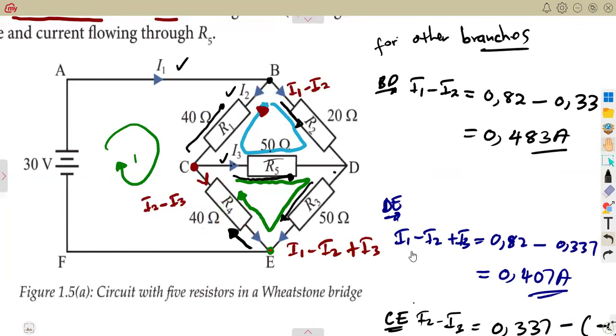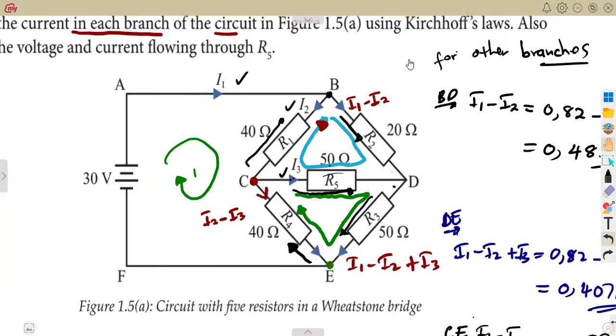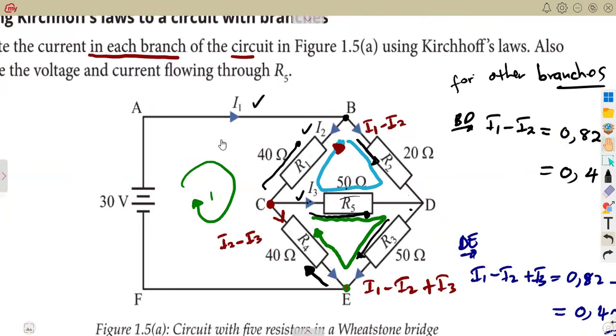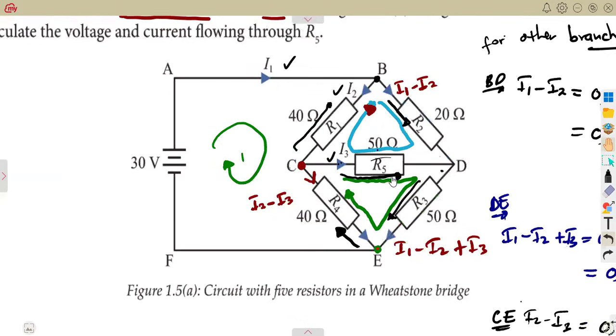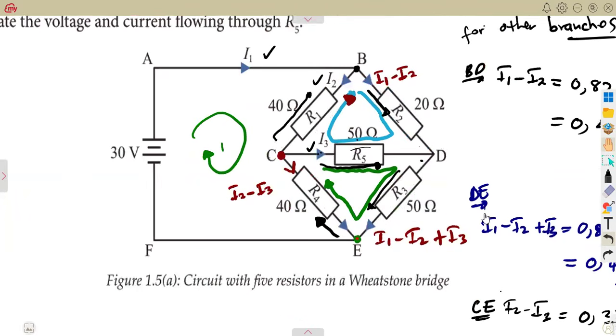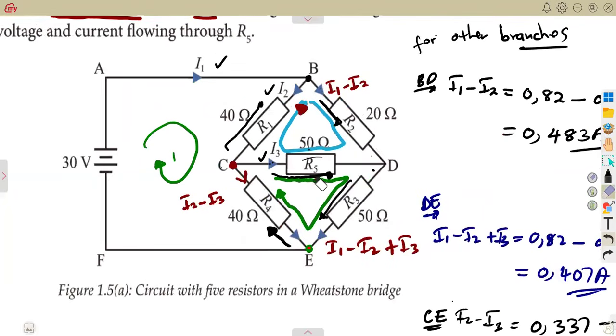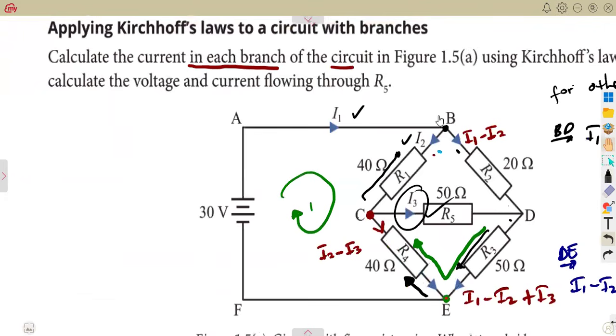Then after, they also need you, using also the Kirchhoff's laws, to determine the voltage and current across R5. All right. So the current across R5, guys, this is I3, so already calculated. The current across R5 is our I3 that we calculated before. So the question was actually supposed to be voltage and power there, because we had calculated all these currents.